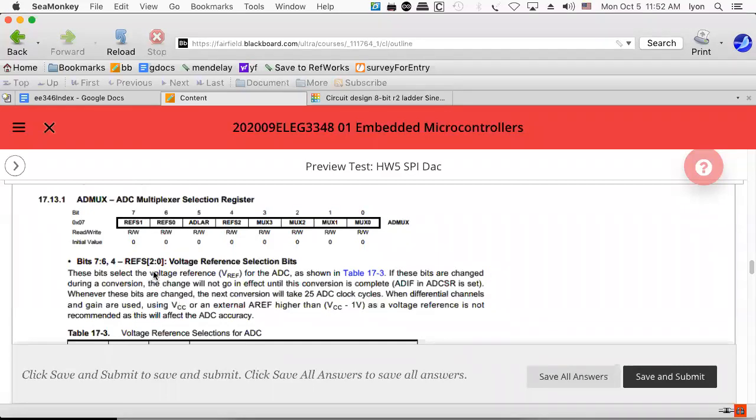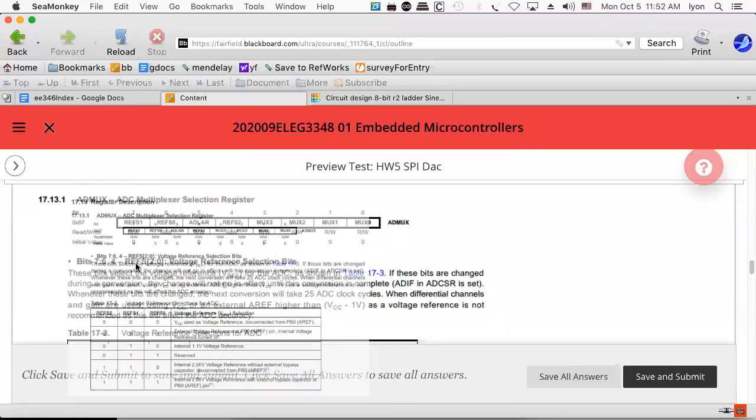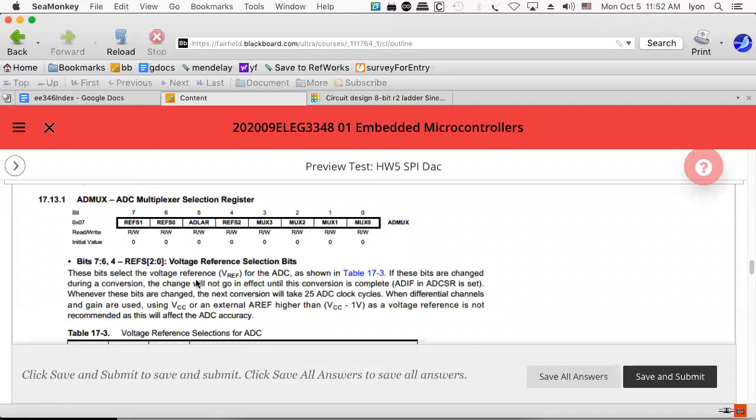And it says here, I can use an external analog voltage reference when doing A to D conversions. In other words, let's assume for the moment that you want to jam out with your guitar. Right? Well, your guitar is not outputting a voltage from 0 to 5 volts. So you run it through a preamp. Well, it's still not outputting a voltage from 0 to 5 volts. In fact, you're lucky if you can get plus minus 1 volt peak to peak. So the A to D converter, well, it wants 0 to 5 volts, unless you set the voltage reference up. If you set the voltage reference up to an external voltage reference, then you can let the A to D converter float relative to the power supply of the Arduino.